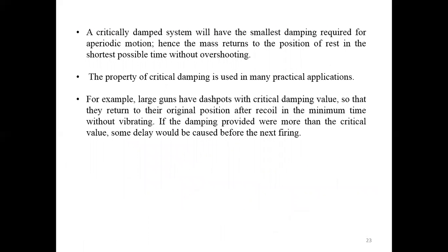Now a critically damped system will have the smallest damping required for aperiodic motion, hence the mass returns to the position of rest in the shortest possible time without overshooting, right? Critical damping means what? You require minimum damping to balance the vibrating body, right?